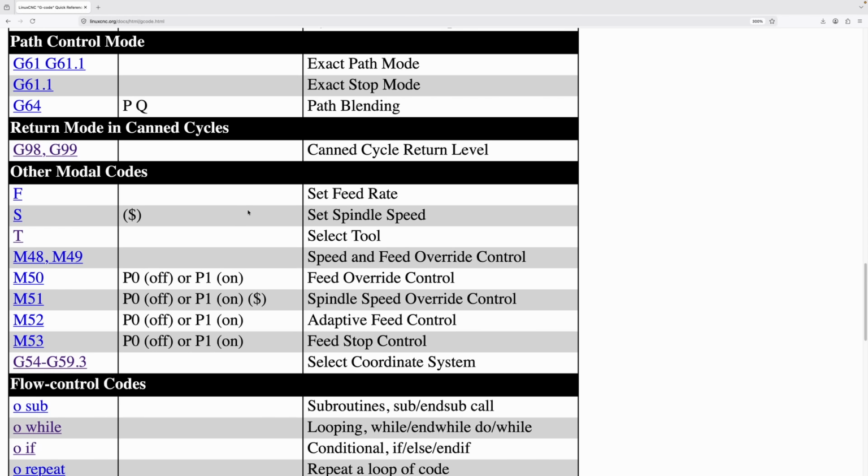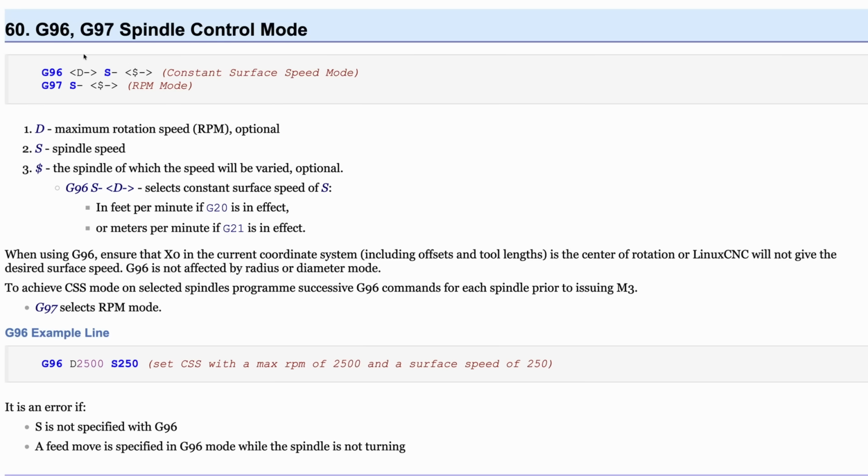So what's the problem, you might be wondering? LinuxCNC's been able to control spindles forever. Within a CNC machine, you usually use the S word for spindle speed, and you just command whatever you want. Speed 400, speed 800, whatever your machine's capable of. That's at least in the G97 mode, which is just ordering an RPM.